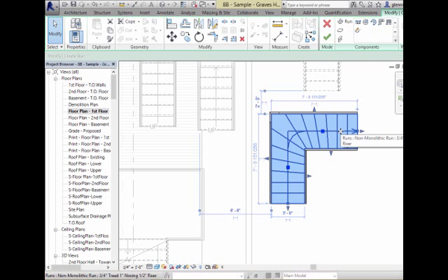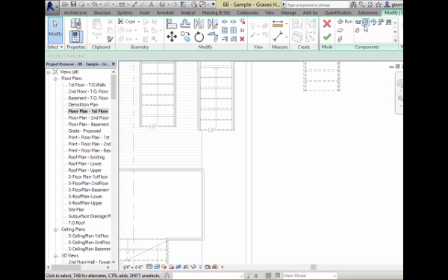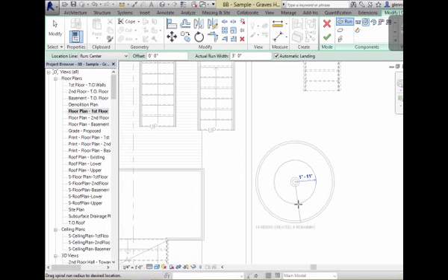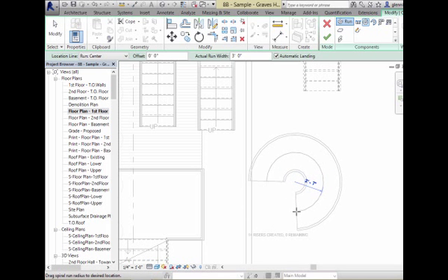The other type of stair that a lot of people like to play with is some sort of circular stair. The circular stair, we can specify by choosing a center point and pulling out. Okay. And that's a full 14 risers at the same time. So I just say where I want the bottom of the stairs to be. Notice it's doing an interesting thing. If I get real tight, you see this is going to be a full 360. If I go further out, it doesn't actually make a full 360. And let's talk about that.